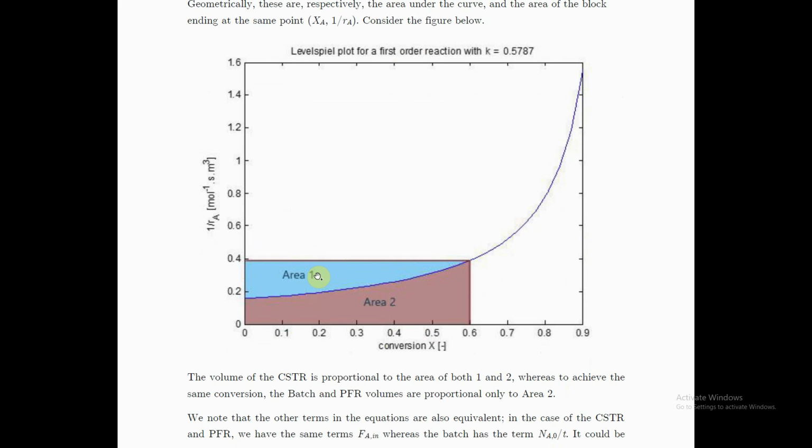And we said we anticipate that's true because the CSTR is stuck everywhere at the same concentration. Remember, the CSTR is perfectly mixed everywhere. So at steady state, you achieve a certain conversion, in this case 60%. There's a 60% conversion in your CSTR everywhere at all times. That means you only have 40% of component A, your reactant, in that reactor.